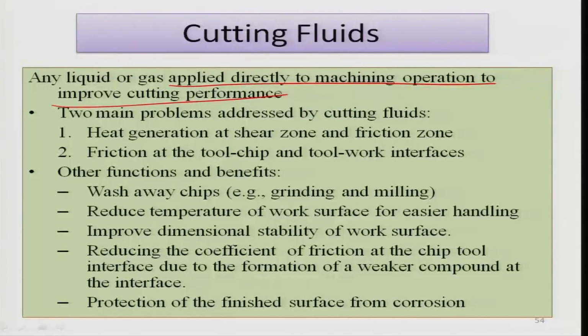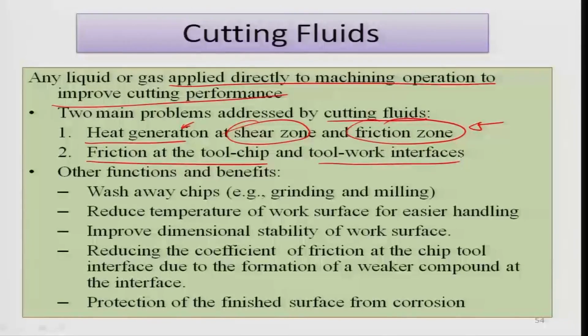The two main problems addressed by cutting fluids include the heat generation, particularly because of machining, that there is a shear zone and a friction zone where a lot of heat is generated. And the other problem is obviously the friction at the tool chip and the tool work interfaces, which again causes abnormal rise of temperatures in the cutting zone, and by putting cutting fluids you ensure that machining operations become smoother.